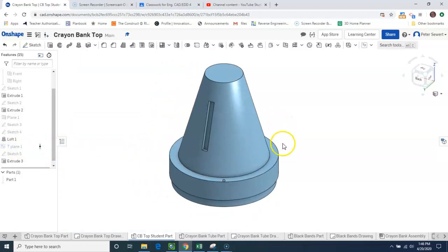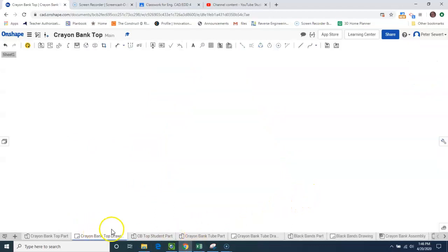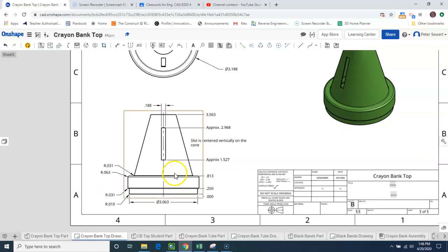And now I have to just put on fillets and radiuses. And you know how to do fillets already. They're all called out on here. They all happen on this bottom left-hand side of the drawing is where they're all called out. You could put those on yourself, and we are done with this part. So you can save it.